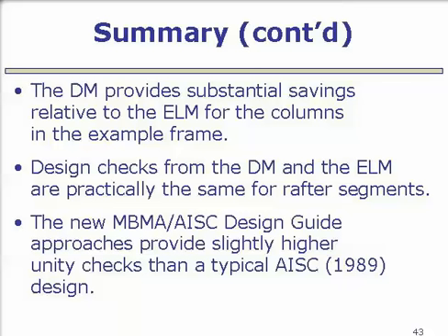The direct analysis method provides substantial savings relative to the effective length method if the calculations of the stability effects are all done on a level playing field. And the design checks from the direct analysis method and the effective length method are practically the same if you're looking at the rafters, but it's fairly common that you may see a little bit higher strength ratios in the rafters with the direct analysis method.